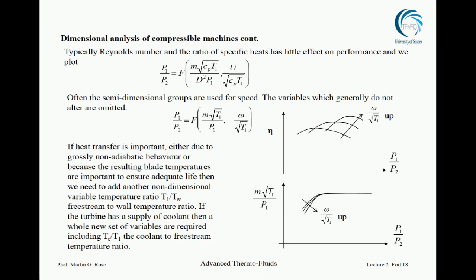I think in practice your intuition that they ought to be related is correct, and that for good operation of the machine, you probably will scale volume flow rate and rotational speed. But in fact, they're independent. You can change the rotational speed by putting more fuel into your engine. It will change speed. You can change the volume flow rate by opening and closing a valve. And so you might keep them in ratio, but you might take them apart.